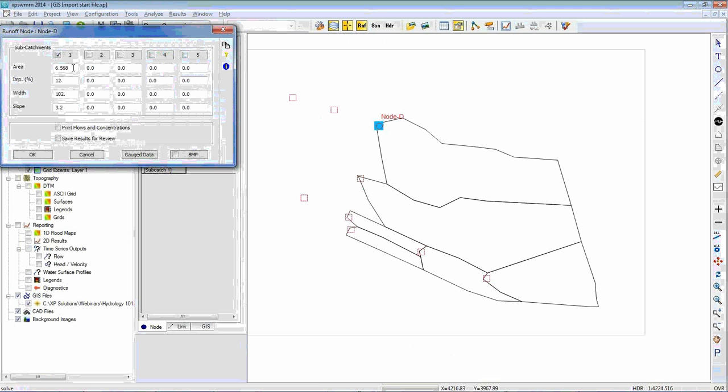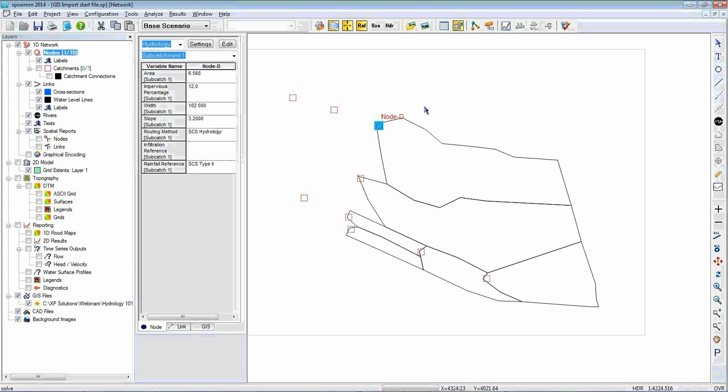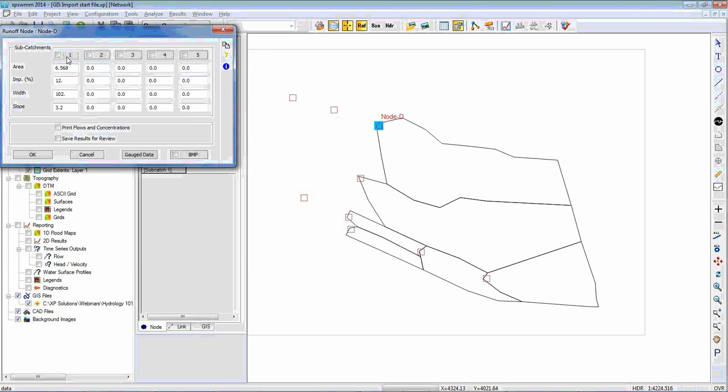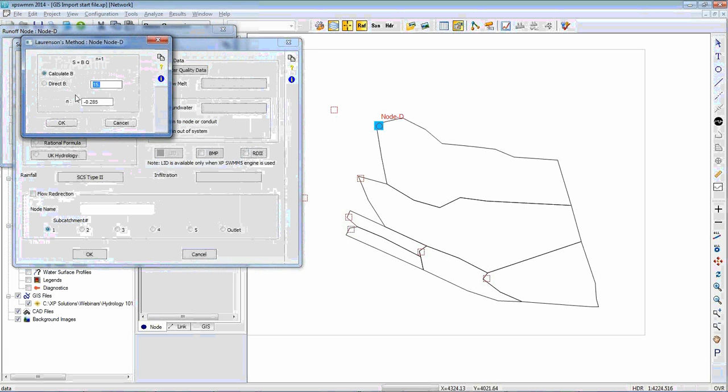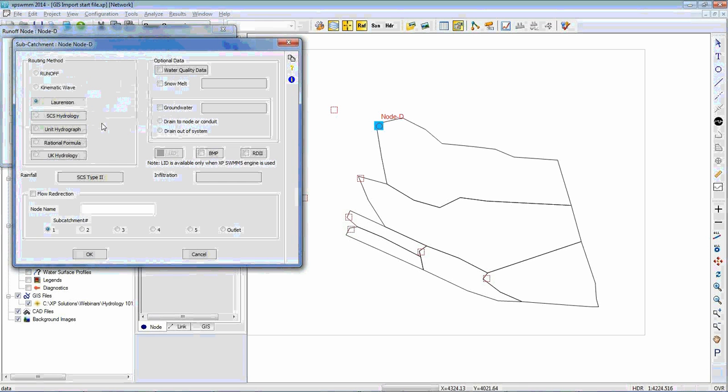only relying upon the core information being catchment area, fraction impervious, which wasn't actually applied to the SCS method, so that number wasn't particularly important, but also the catchment slope. The other hydrology methods available to us also include, as described before, Lawrenson's method here in Australia. Lawrenson's method has enough information to calculate the B value, which is the critical parameter for the storage equation. That's important. There's enough information inside the software to derive that automatically, and we can then select any rainfall.